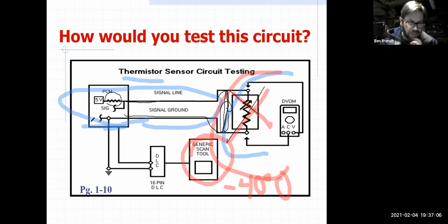In fact, that's how it knows, I won't get into how it's a voltage divider circuit anyways. So I throw my paper clip in there, and now the computer should say, oh man, you're like 300 degrees. You're smoking hot. Okay. Well, if it went crazy cold unplugged, and if it went smoking hot when I give it the J tool, right, which is our automotive name for a paper clip, you can't just tell a customer, oh yeah, I threw a paper clip in your car, they're going to think this guy's a crazy man, right?